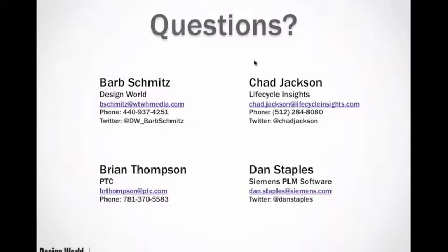I would just add that I don't think it's, to be honest, any contest. If you were reading in data from another system, and you could choose to read it into the history-based environment or the non-history-based environment, definitely read it into the non-history-based environment. You have much more flexibility and ability to make the changes you want to make.